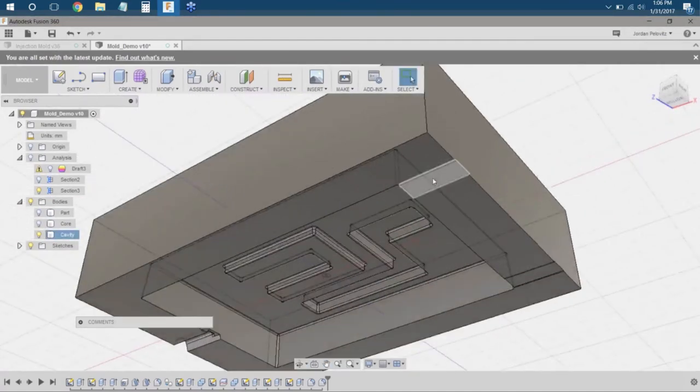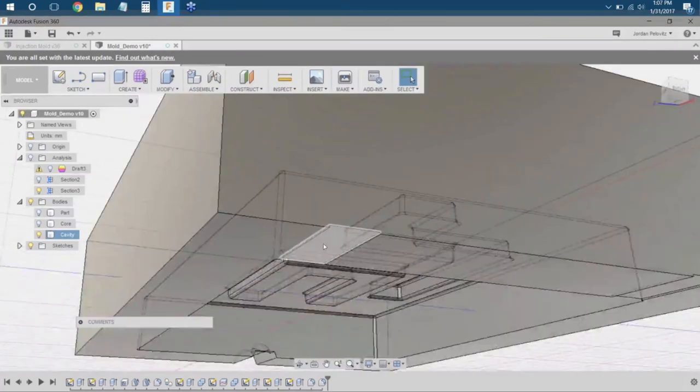With the runners, with air vents, you also kind of want to only put them on one side. You don't really need to put them on both sides. So sprues and gates and stuff like that, they go on both sides. Runners really only stick to one side. And you can think of them kind of like flash on purpose. You want them just tall enough to let air out, but not tall enough to let a lot of plastic out.